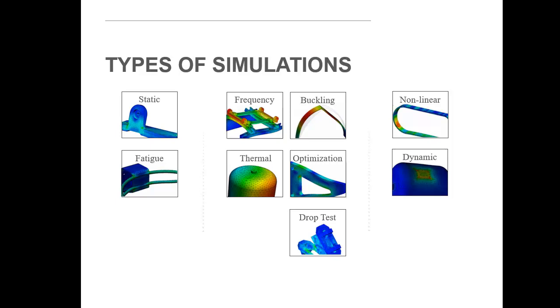In the fatigue module, we look at the effects of cyclic loading over time and the damage done to the material because of that. Fatigue life to failure can be a useful metric to determine the expected lifespan of your component. The frequency module calculates natural frequencies and modes of your structures. This can be useful for analyzing components and structures that operate in vibrating environments, for example cars or other vehicles, or machines such as milling machines or 3D printers, to make sure the component or structure doesn't have a natural frequency close to the operating frequency of the vehicle or machine.